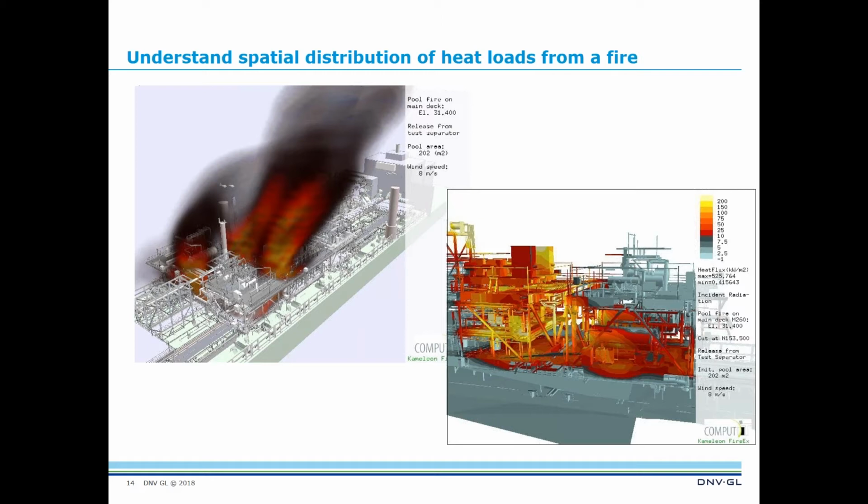And to the right, a more quantitative result from the same simulation, showing the heat load footprint directly to the topside structure. So you can get a very detailed picture of the heat loads to the various parts of the structure, including shielding effects and things like that. So you can see how large part of your structure is exposed to actual critical heat loads.